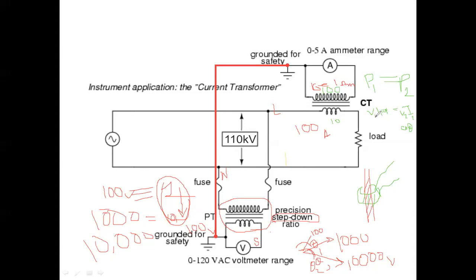Look here, V1 I1 cos phi equal to V2 I2 cos phi. So if P1 equal to P2, then cos phi is the same on both sides. So if here I is much higher, at 100, you have to keep V small, and in the secondary case we need to reduce the I. So if I reduce the I, we have to increase the voltage level.